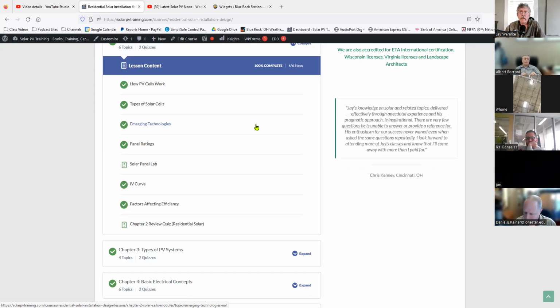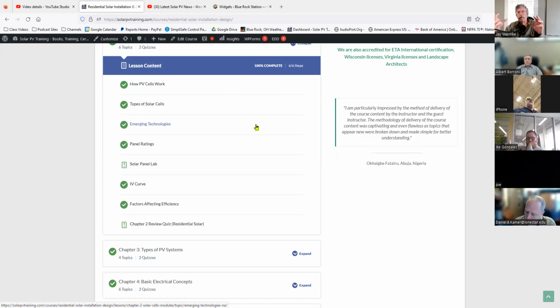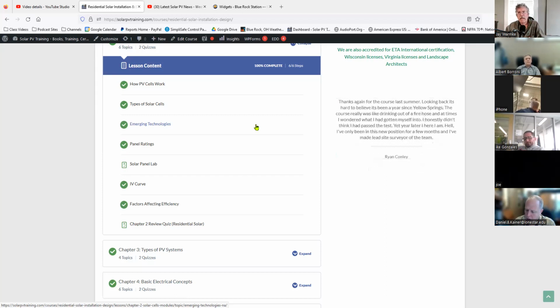They offer a 30-year warranty, and at the end of that warranty period, your panel will produce 90% of what it produced when it was installed. So that is far and away the best warranty out there in the industry. And this is for a thin film panel. Plus, the thin film panel is only like 6 millimeters thick versus 35 millimeters for a silicon solar panel because of the frame. These are frameless panels. They're basically glass on glass with an inkjet printing type membrane in the middle.